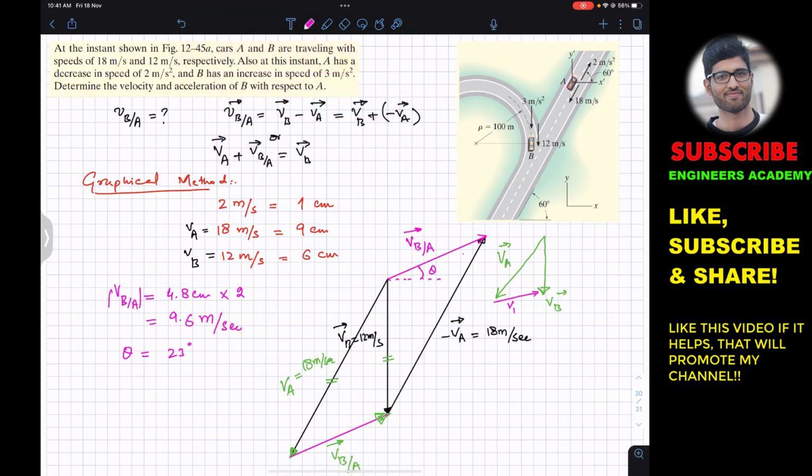So this is VBA. So this is the easiest method. Do not alter the direction of the given velocities. Just join them at their tails. And then if you want to find the velocity of B relative to A, start a vector from the head of A and end it on the head of B.